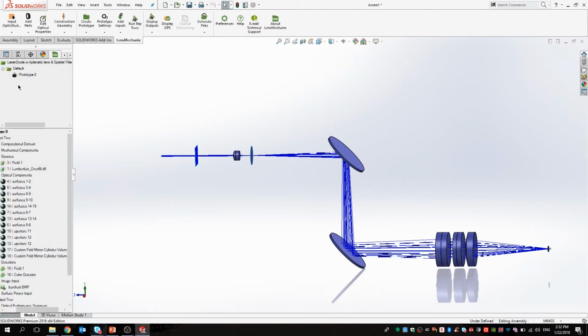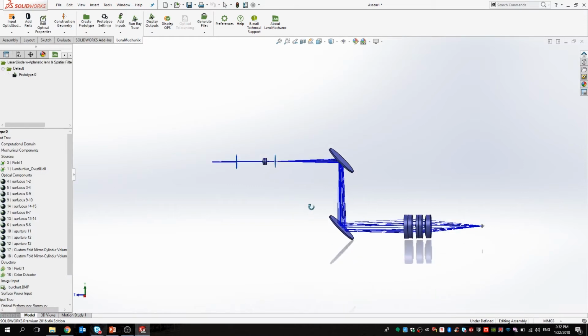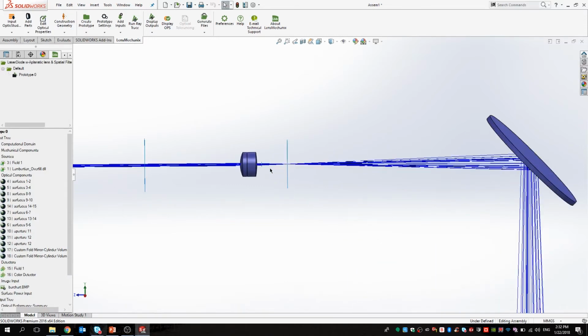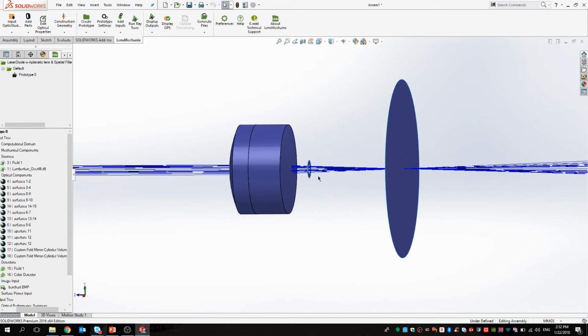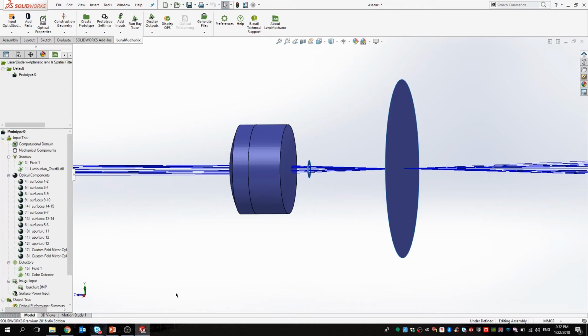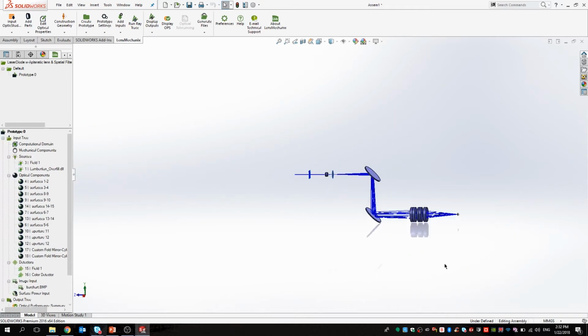Okay, with the second ray trace complete, we can see that our optical train has been modified to include our two references. What I like about this example is that it has the annuli, which will verify that our performance is the same after adding fold mirrors as it was before. Therefore, we've maintained the alignment throughout the system.